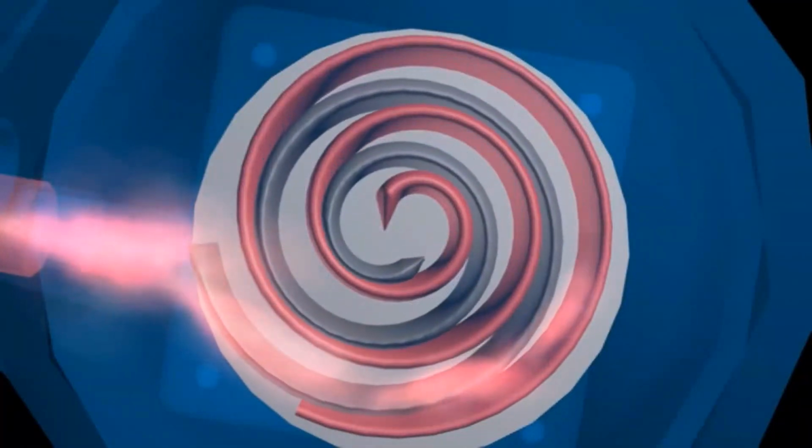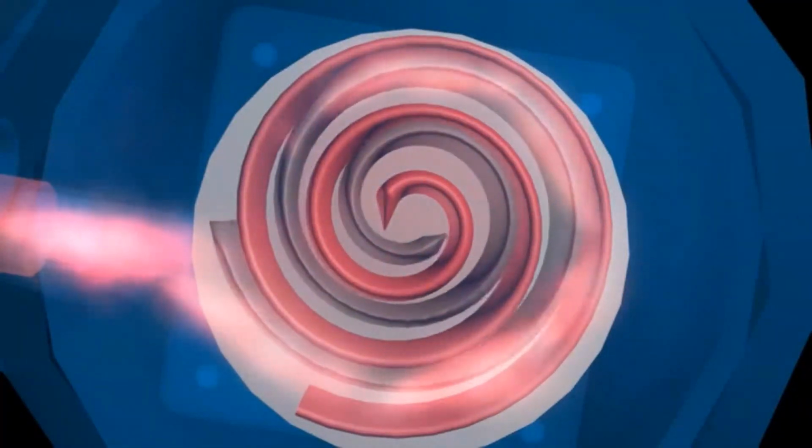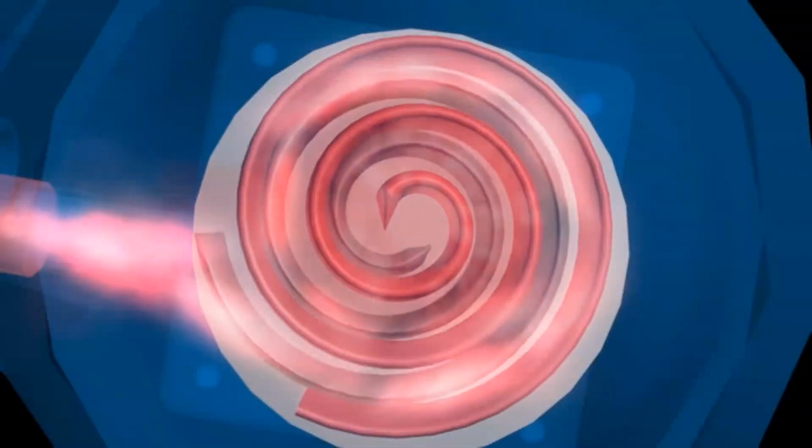The type of compressor used was the scroll hermetic type. The scroll compressor works as follows: gas at low pressure and temperature enters the suction line and goes into the compressor. The low pressure and temperature gas is pressurized by the scroll compressor to high pressure and temperature gas. The high pressure and temperature gas is then passed through the discharge line and goes into the condenser.